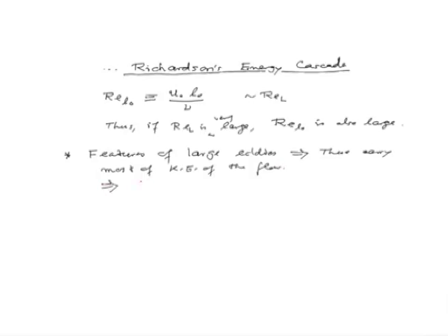The next feature is that these are unstable. Instability is what drives the turbulent flows. So, these break up into smaller eddies to which they transfer their energy.